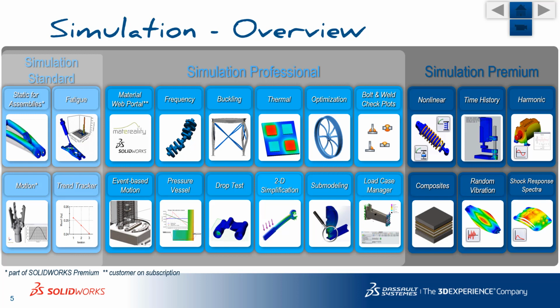You have your nonlinear material models, whether that's nonlinear elastic or nonlinear plastic, right? So we can talk about post-yield behavior of our materials, nonlinear boundary conditions. Maybe something is suddenly applied or applied over time. And then we get into dynamic studies.